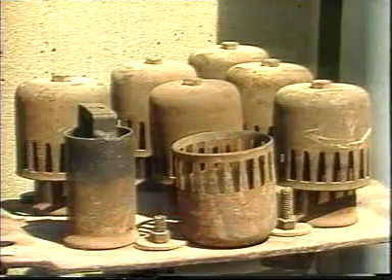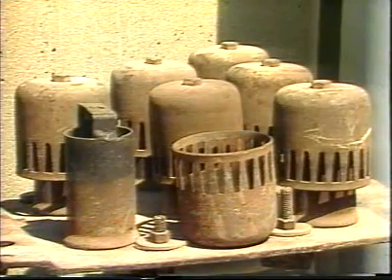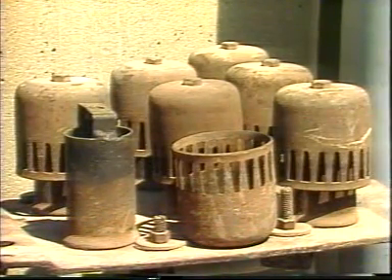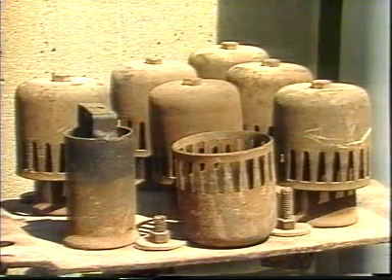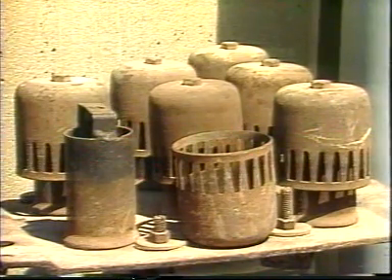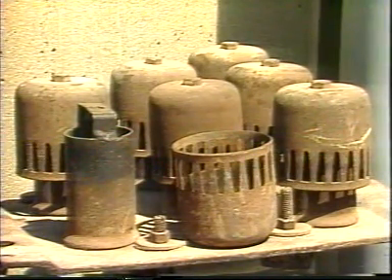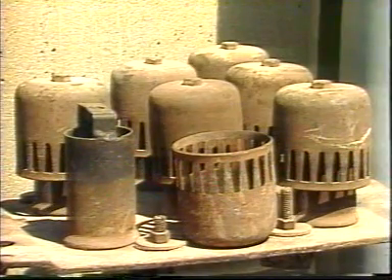This footage shows what the inside of a distillation column actually looks like. The column is sectioned into a series of chambers that are separated by trays. Liquid reflux moving down the tower flows across these trays into downcomers, which lead to the next lowest tray. On each tray there are a number of openings, like these risers and bubble caps, that provide a passageway for vapors to rise upward in the tower.